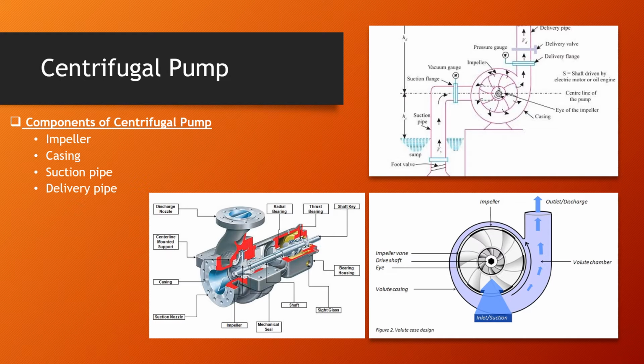Then you turn the impeller on with the delivery valve closed, so there's no delivery. Now the rotating motion of the impeller would start imparting energy to the fluid, and it will start displacing the fluid towards the impeller end, and will impart centrifugal motion to it, and it'll start hitting it into the casing.